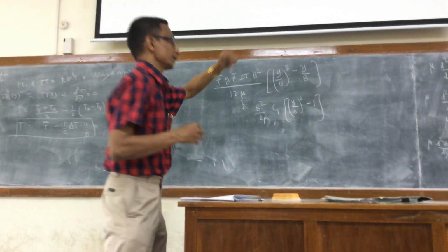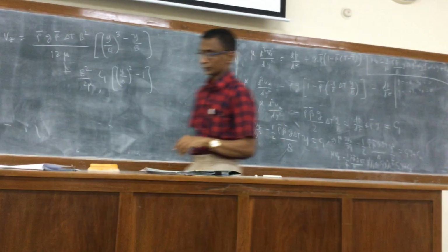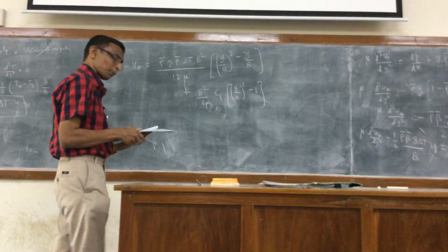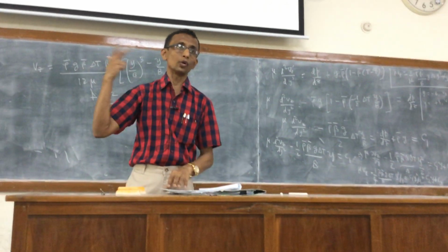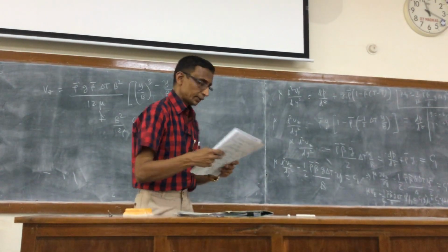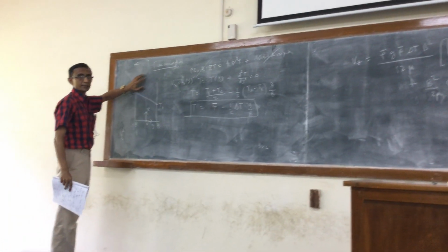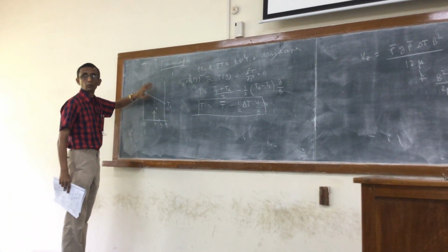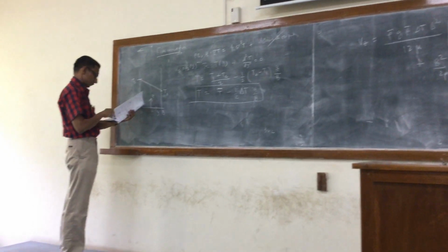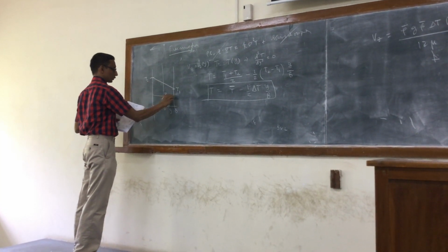If you apply the no-slip boundary conditions, 2 of these constants can be determined. The other constant, C1, we determine by the following condition, an approximate one again: that the net mass flow across any cross section is 0. What he is effectively saying is that the fluid being heated will go up, then it has finally come down. So the velocity profile looks somewhat symmetric. Actually you can see that the profile would look something like this.